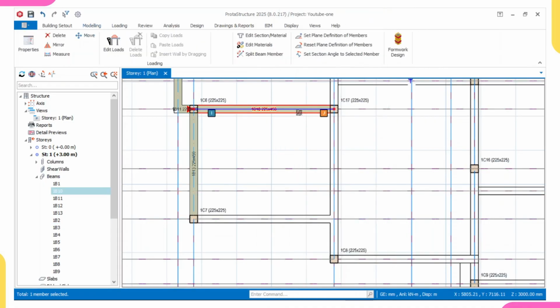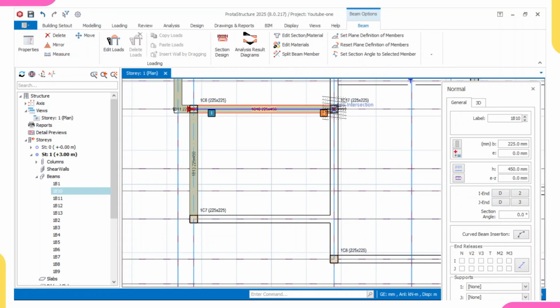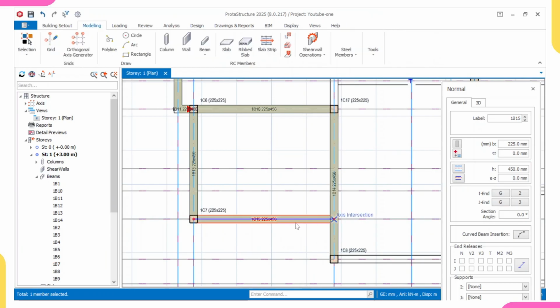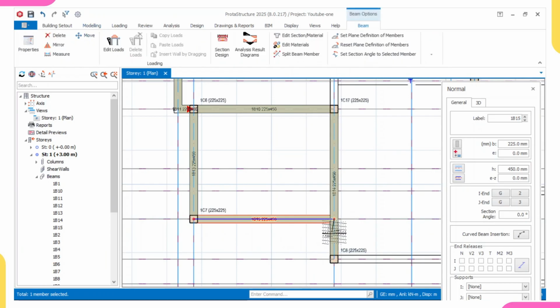So I'll double click on this one to bring out this property. I'll first of all connect a beam to this. So I'm having this now. Then I'll come and connect this. If you can see now, that arrow sign is no longer showing. The reason is because we have not made this beam a secondary beam. Look at this beam now, it is a primary beam.